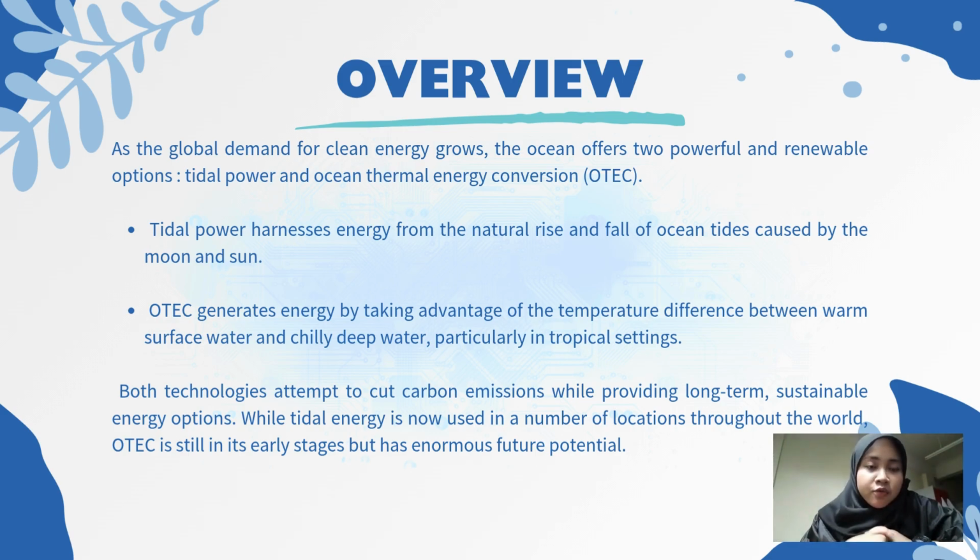For additional information, ocean thermal energy conversion, or OTEC, systems employ a temperature difference of at least 20 Celsius or 36 Fahrenheit to power a turbine which generates electricity. Warm surface water is pushed through an evaporator with a working fluid. The vaporous fluid powers a turbine or generator.